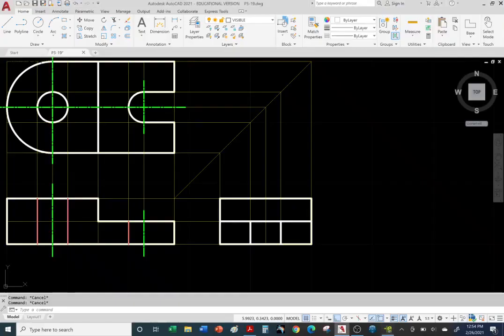All right, so it lines up with this hole, right? So here's this construction line, this one, and this one. Hit the 45 and come straight down. And this is where we have that hole going all the way through the top, exiting out the bottom. So instead of having to draw from scratch, I'm just going to copy the one we have here on the left. It's the same hole. The same hole you see here in the front view, it's the same one you're going to see here on the right side view. Same one that we see here in the top view. So I'm going to cheat. Just don't tell anybody. Hit escape. It'll be our secret, right?